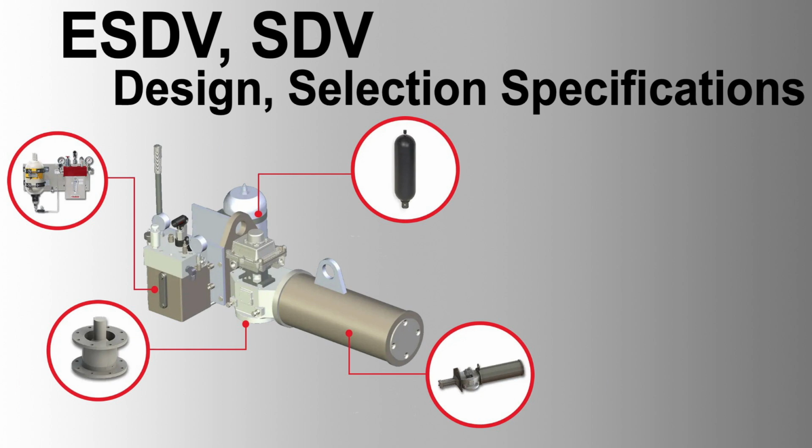Pressure rating: typically designed to handle medium to high pressures, often adhering to standards like ANSI/ASME B16.34. Temperature rating: suitable for the operational temperature range of the facility. 2. Trim: material: corrosion-resistant materials such as stainless steel, Hastelloy, or other alloys to withstand the corrosive nature of crude oil and process gas. Design: trim parts, seat, disc, stem should ensure tight shutoff and durability under frequent operation.